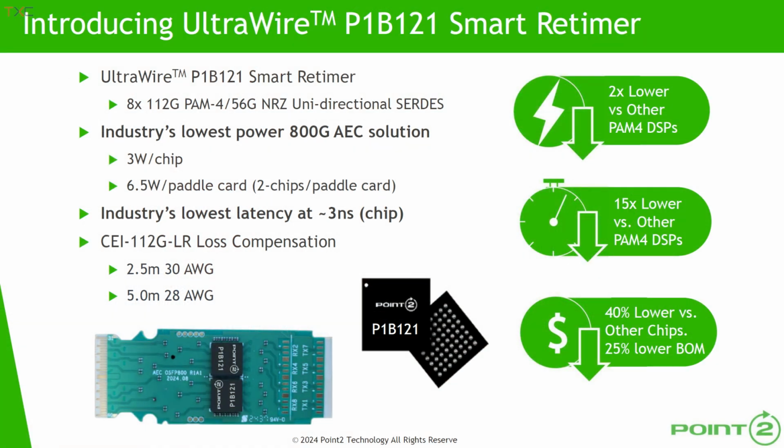Now, in terms of implementation, a lot of people have been trying to implement the PAM4 that's being used here using DSPs that I think have also been used in optical modules, but you're taking a different approach. Oh, absolutely. And this is where we're taking the purpose-built approach. If you take a step back, optical cabling technology has been around for many, many years. And what's in those optical modules is an optical DSP to take care of the impairment, the loss over the fiber cabling.